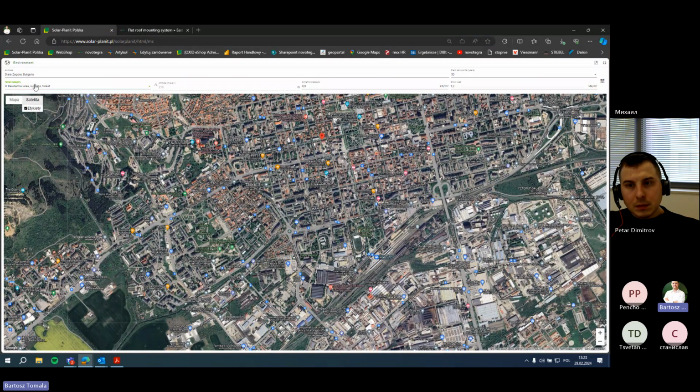So there is a possibility for higher or lower impacts of the wind, for example. If we have an open area, there's a higher possibility of huge wind speed hitting the construction, and we have to put more ballast, of course, to compensate this risk, especially with a 50-year lifetime.